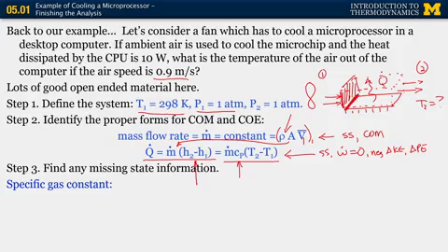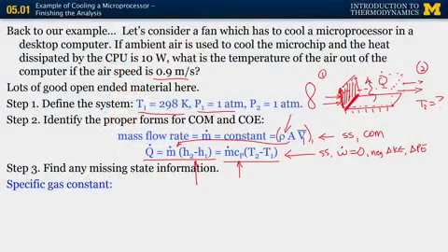Now, in terms of the dimension above the surface of the CPU, the heat transfer occurs entirely within what's referred to as the thermal boundary layer. So we would need to have some estimate of what that distance is for the thermal boundary layer. For this problem, we're just going to assume a good number. If I assume that this dimension here is about 2 centimeters, I assume this dimension here is about 1 centimeter.